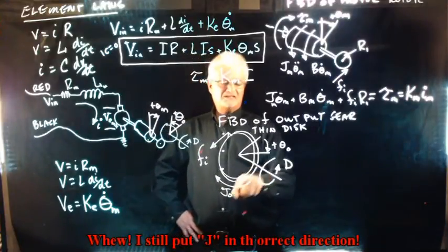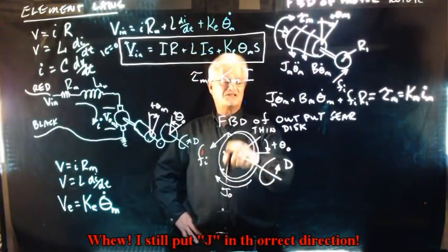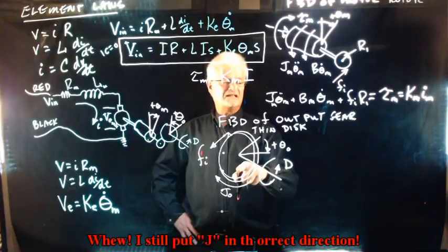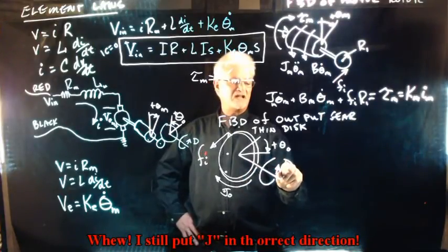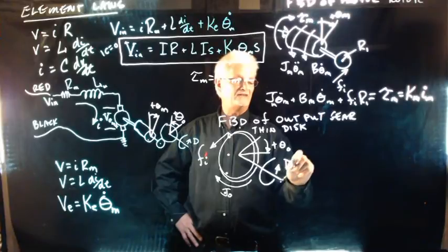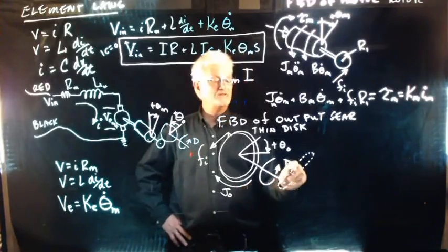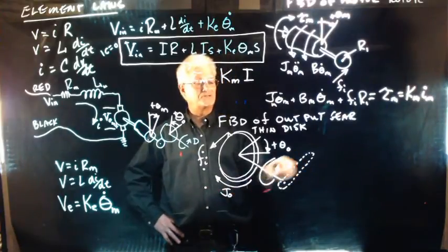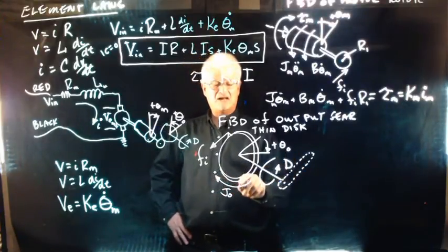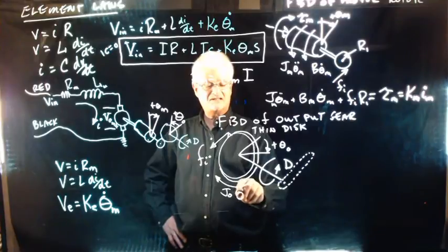Notice that this J for the output gear could just include the thin disc. But if you're making a robot leg out of it, you might also have some kind of big bar on here, and we'd use that output inertia to include whatever inertia happens to be on here. So this is J out, theta double dot out.